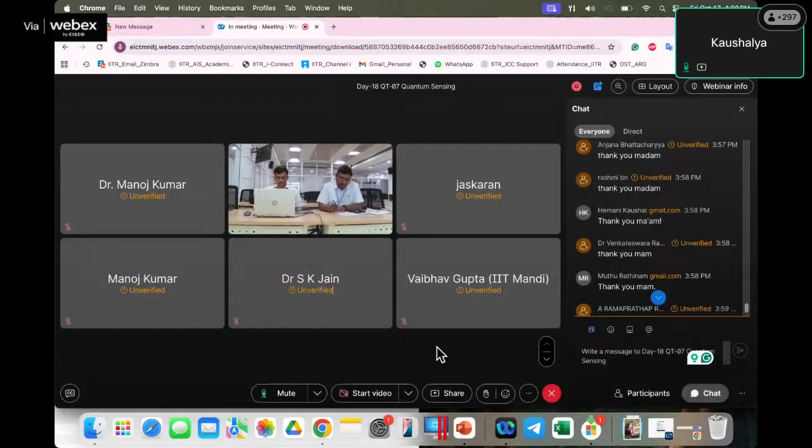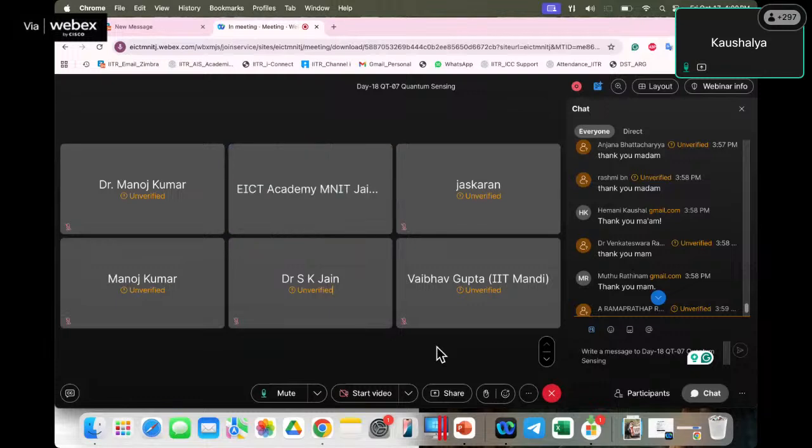In this particular study, we were using indium gallium arsenide based cameras. They are not popular to be used in the telecom band, and there are even better options to use. And then another aspect to look into this issue is how well can you even collect the photoluminescence from silicon, because silicon again is basically not a material that is known for light emission. So that is another aspect of looking into it.